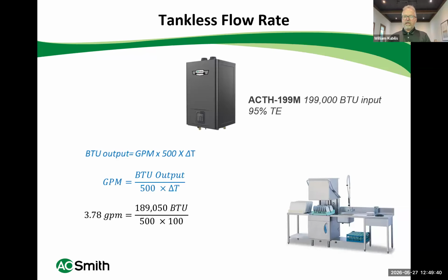In this case, I've done the math already for you. An ACTH 199 will deliver roughly 3.8 gallons per minute of hot water. That's it. It will hold the water back to deliver my 140-degree water.